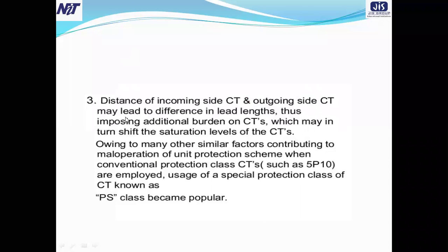Now, number three is that the distance of the incoming side CT and outgoing side CT may lead to a difference in lead length, thus imposing additional burden on CTs, which may in turn shift the saturation level of the CTs. Owing to many other similar factors contributing to maloperation of unit protection schemes when conventional protection class CTs such as 5P10 are employed, usage of special protection class CTs known as PS class became popular.